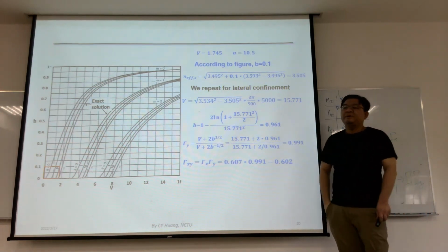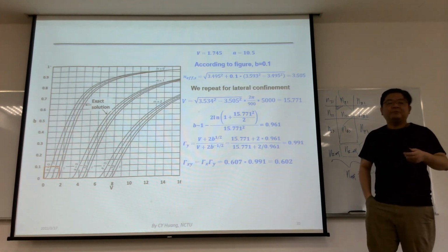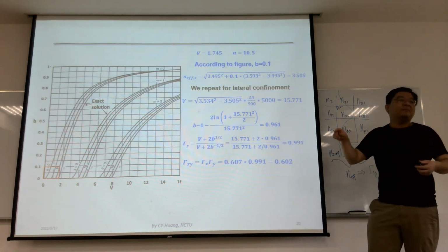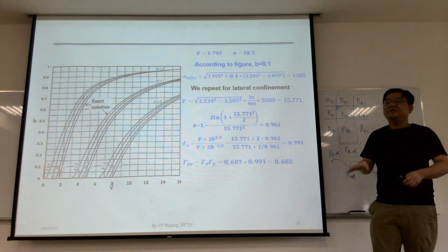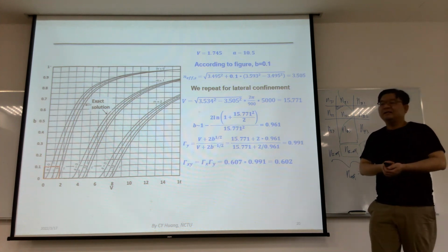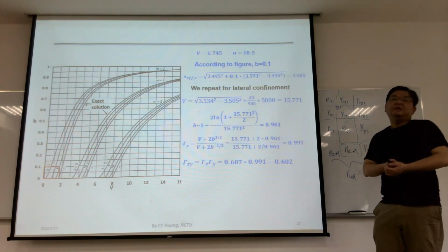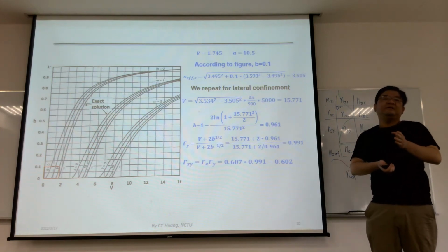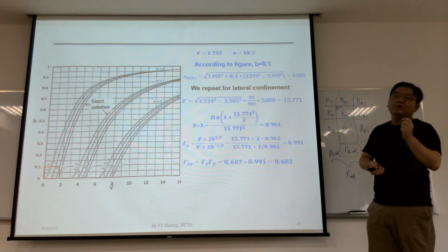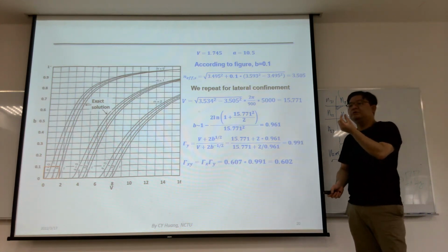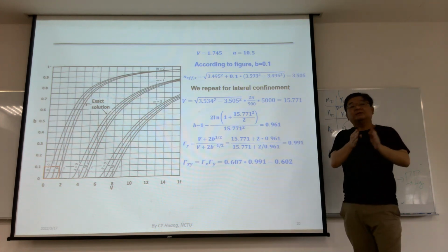So this will explain why a single mode laser, after you finish this, probably you can try to read some numbers of the lasers you can buy on eBay or Google. Actually now you can buy semiconductor laser diodes from the internet. And if you see a ridge waveguide laser that is said to be a single mode laser, to make a single mode you need to make a narrow ridge to confine the optical mode with only one solution.